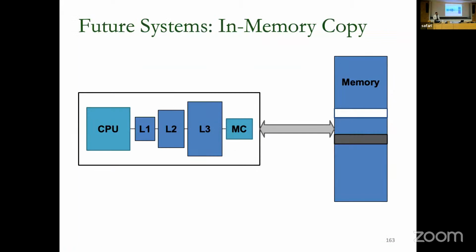And in the way that this is done today, you have your processor, you have your memory, and you have a bus to communicate between the two. If you want to copy a memory location to another memory location, the CPU needs to read the data. Basically, from the CPU point of view, you need to read this block from memory into the cache hierarchy, get to the CPU, then write to the new location and move the data back to the memory itself. Even if you want to copy just a small portion of the data, you need to go through this process, which is quite high latency because you need to read through this bus that is quite slow, into the CPU through the cache hierarchy, and it also consumes a lot of energy.